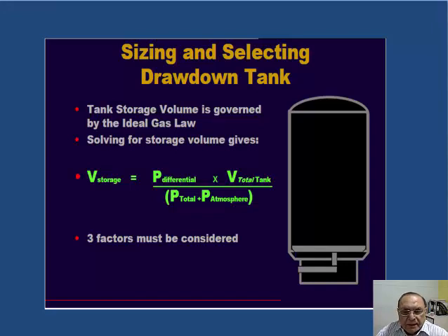This is the drawdown tanks, and how do we select? What are drawdown tanks? See, the drawdown tanks are required mainly for 2 purposes. One is to supply a small leakage without running the pump. The other is that any kind of water hammer and other things are absorbed because of the pumps running and closing.